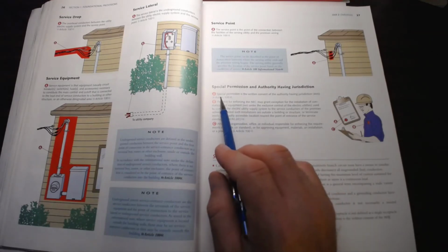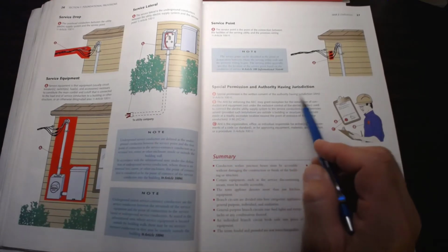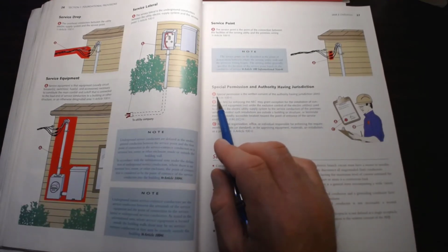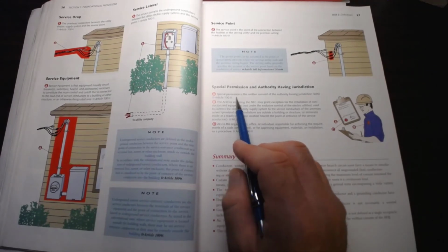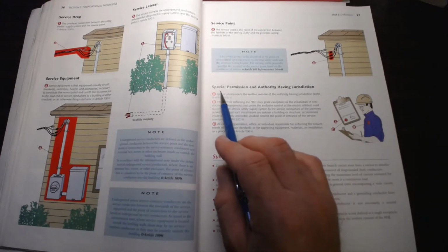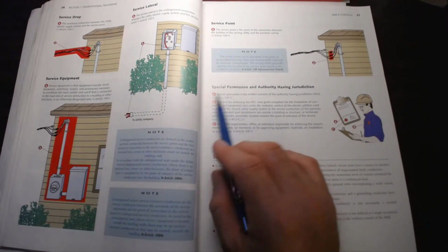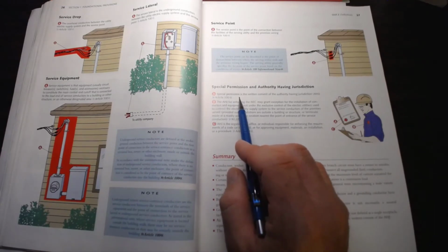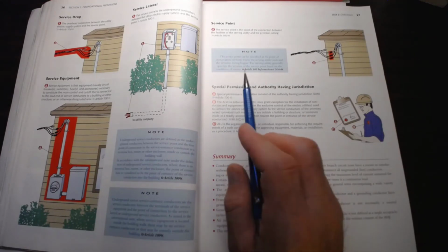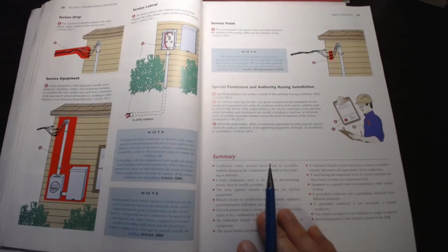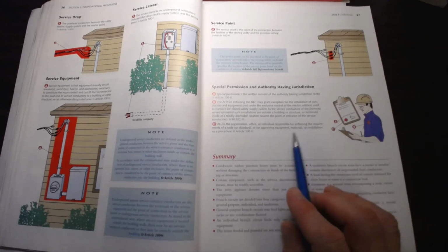So the other thing I want to point out here is the special permission is written consent from the authority having jurisdiction. I have never got special permission from an inspector. When I thought I needed special permission, we talked it out. They met on the job site, and we worked out an alternate that they would sign off that was within the code. There is a lot of responsibility on any AHJ to give special permission, and they will err on the side of caution to not even give it. So it's here, it's defined, but it's not something you would typically see. It's always good to have a good relationship with your inspectors.